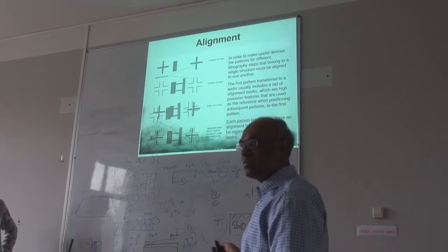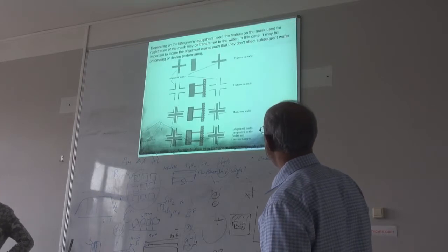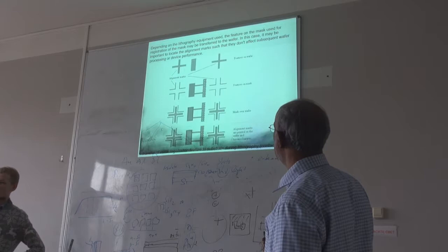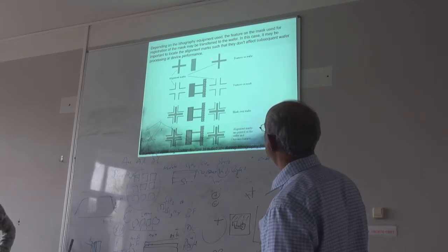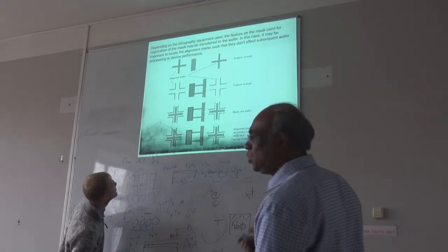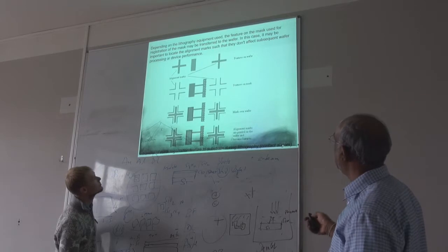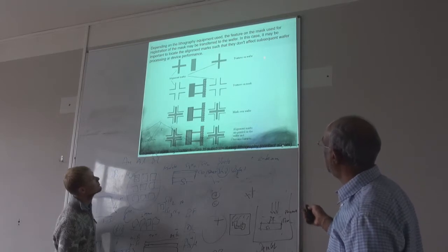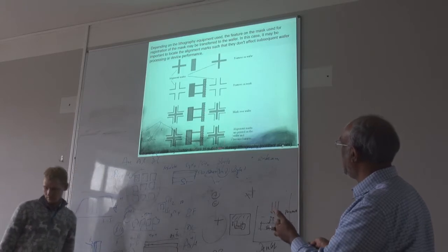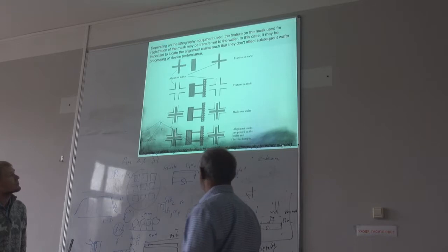Is that clear for everybody, the mask alignment? So I have some even more details on how. Another one, so perfect alignment should be something like this. This is if you use two masks, right? On the first mask you have the alignment mark, this is on the wafer. So this is the feature on your second mask. Then just align the two. Once you get used to it, it's pretty straightforward.